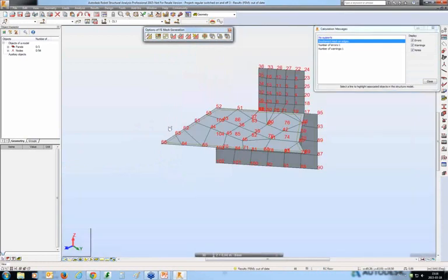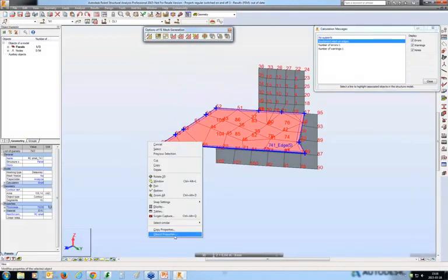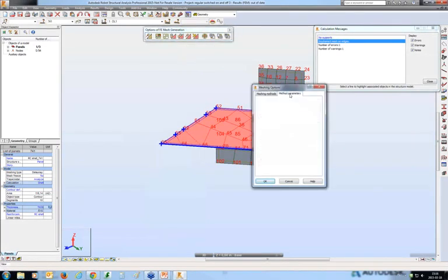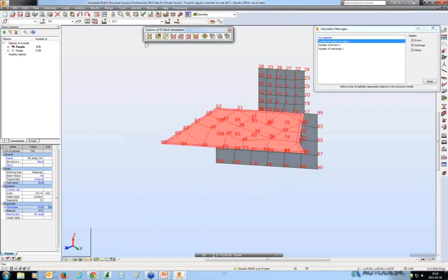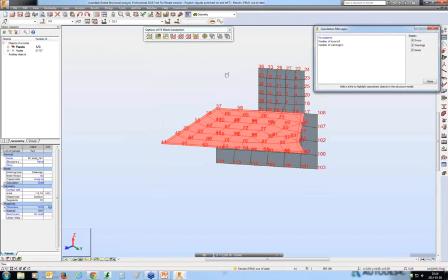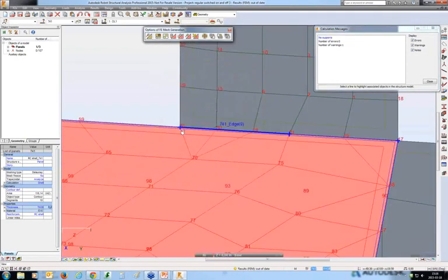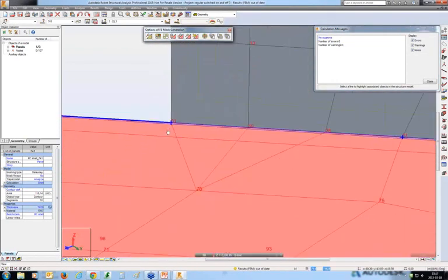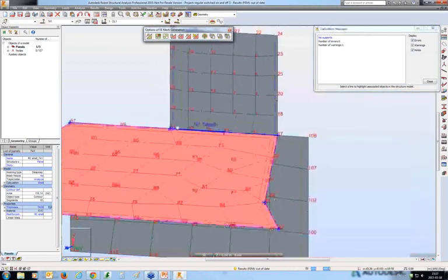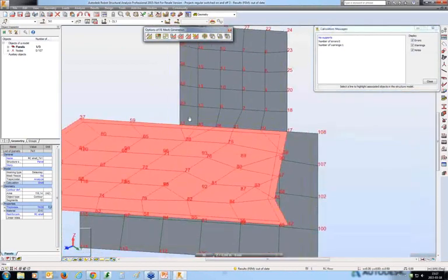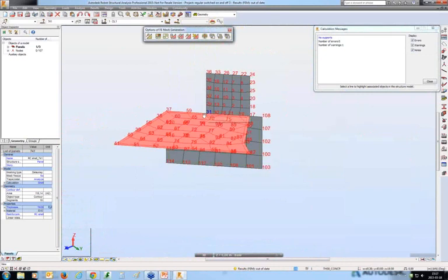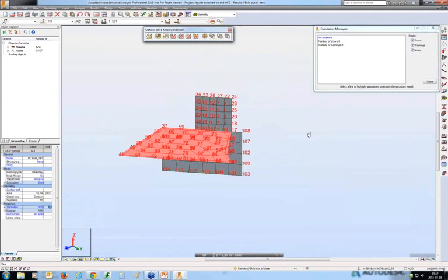So what I'm going to do is check what parameters I assigned to the selected panels. Meshing parameters include regular mesh. I will switch off regular mesh, and I will just generate the model again. And this time, okay, the different algorithm handles the situation in a better way, and there is no excessive number of elements or nodes in this location.